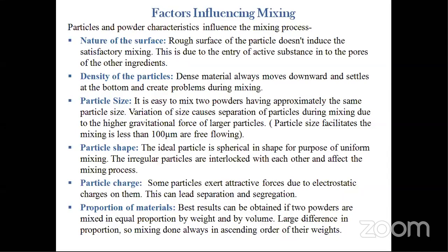The first factor is the nature of the surface. Nature of the surface means the surface nature of the particles. If your particle has a rough, irregular surface, because it has some pores, some porosity present on its surface. So due to the presence of pores on the surface of the particles, what happens during mixing?